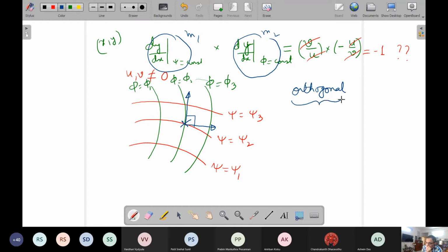So they are orthogonal curves, and the advantage of orthogonal curves is that you can generate one of these functions if you know the other function by using the orthogonality. So if you have two-dimensional, incompressible and irrotational flow, and by some way you have this, then the family of orthogonal curves can be generated, and those will represent the phi equal to constant lines.